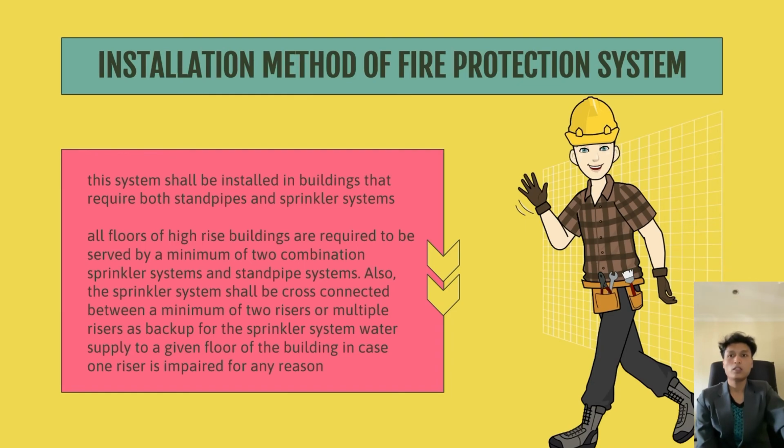Nevertheless, while it is a popular choice among the rest due to its ease of installation and optimal protection, it is not actually suited for all kinds of environments. This is because the pipes in a wet pipe sprinkler system are always filled with water, so this particular system does not work well in areas that fall below 40 degrees.